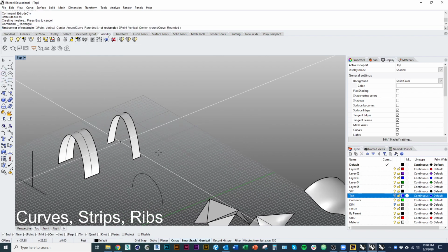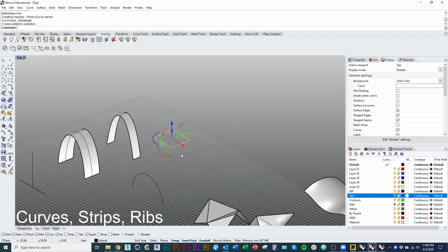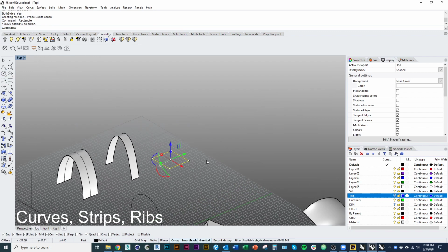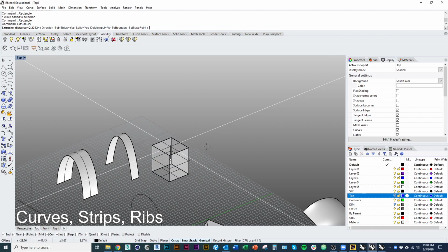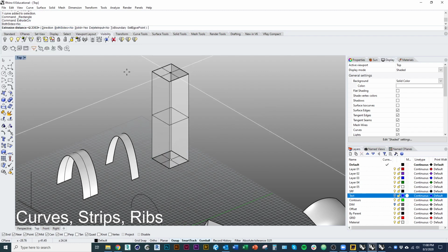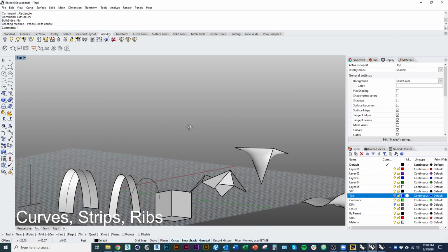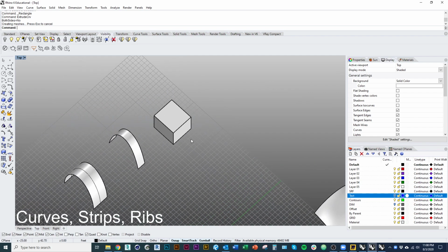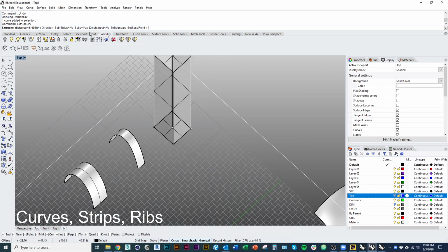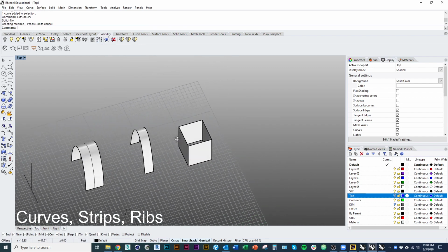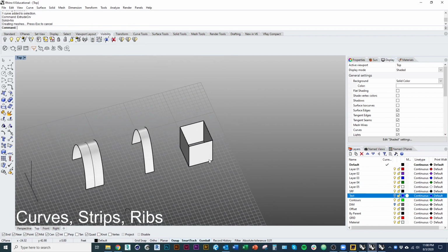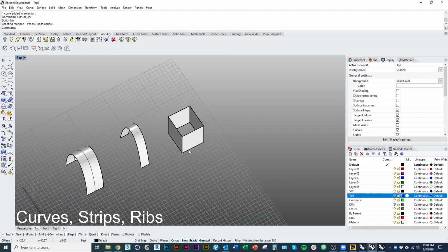And when you extrude a closed outline, for example, if I draw a closed rectangle and go to extrude curve, and I'll turn off both sides, we have this option, solid. Basically, that means when I extrude this, if I have that on, you can see it made a little closed end to my box outline there. If I do that again with solid turned off, you can see I don't have a closed end, I just have an open kind of tube.